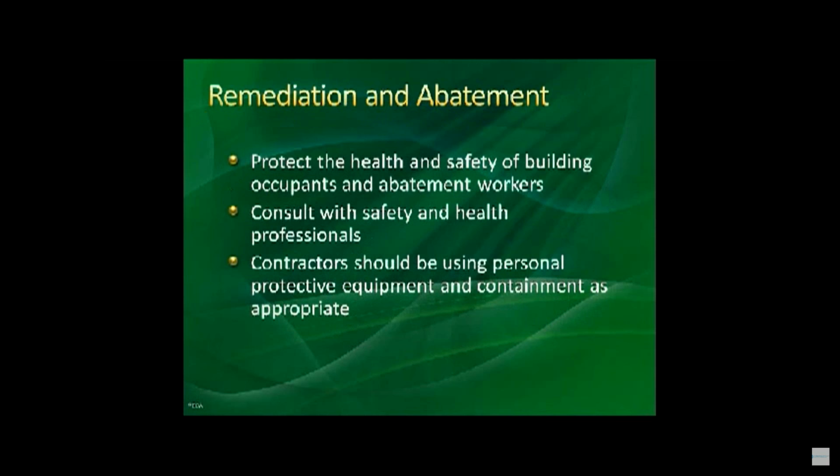A good remediation and abatement is going to protect the health and safety of the occupants. They may want to consult with a health professional before it's done, depending on your client or depending on what they're allergic to. And we also discuss personal protective equipment. You as an inspector need to carry PPE, or personal protective equipment: simple gloves, a half mask respirator, and some goggles or a dust shield for your eyes. Mold can affect you as well.